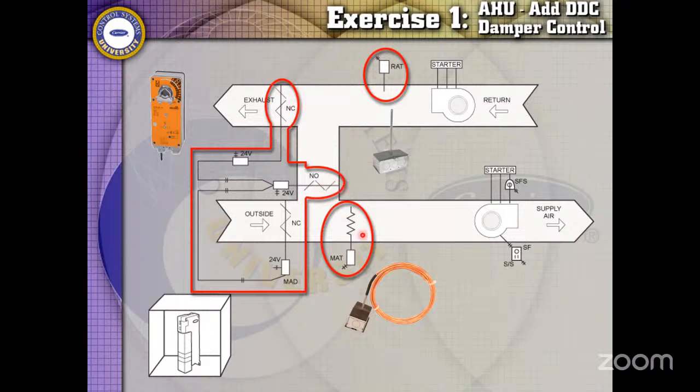You can have each one of these wired to your DDC controller, or you can be cheap and wire all of them to one output on the DDC controller and reverse the action switch on this particular one. I'm saying being cheap, but sometimes you've got a controller that only has 8 outputs and you need 9, and I don't want to buy another controller. So yeah, I'm being cheap by forcing that one to copy his brothers.